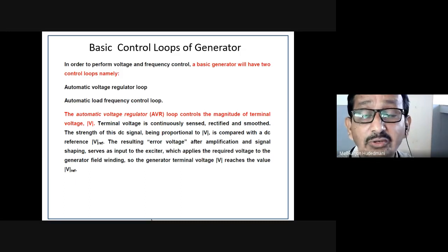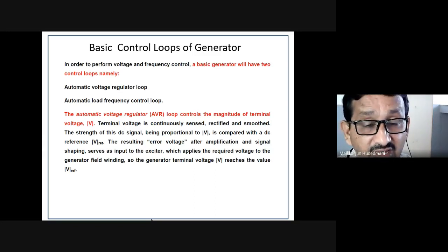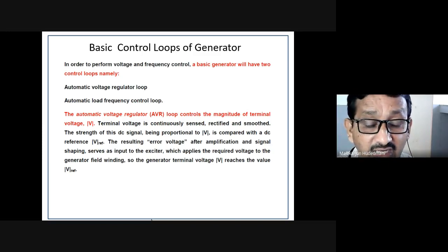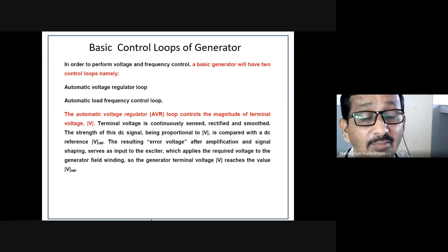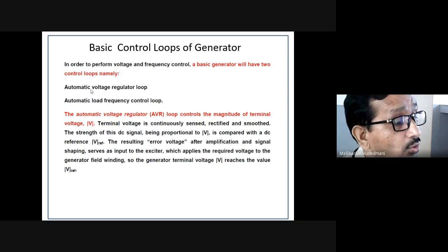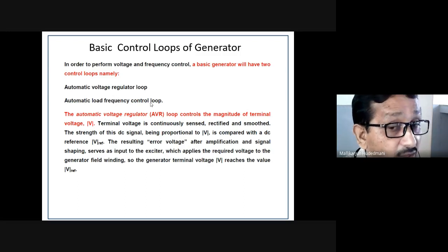You will not be able to maintain the frequency at the specified steady state. If frequency fluctuations are occurring, it is an indicator that your actual megawatt balance is not happening, then it is the concern of this automatic control loop to see that the load, the active power you draw, whose relationship with frequency is monitored and controlled.